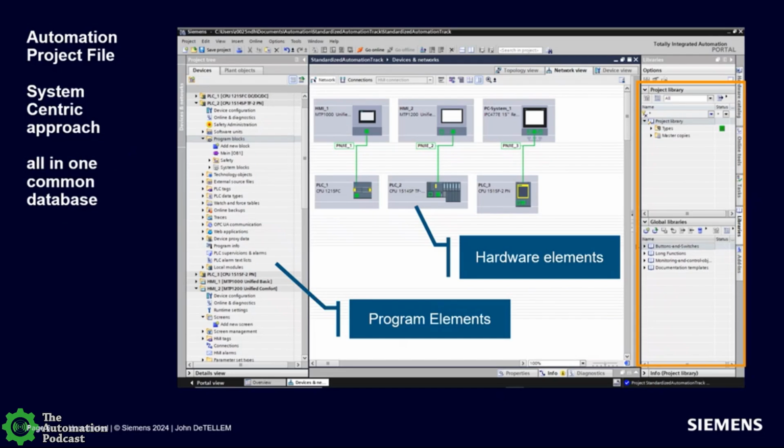And the reason, as you'll see a little later, is that once I have a faceplate or a type of motor control in my project library, that's my master element for all of the instances of it in all the PLCs, basic PLC, advanced PLC. So if I have a robot control in every one of them, I have a reference of that UDT or that faceplate or that motor control in one place. And that one place is this project library. So that's the project library.